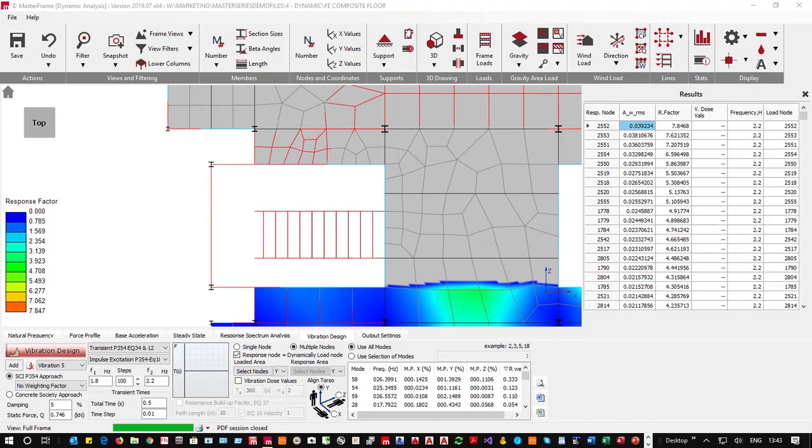Somebody's asking about this effect of the ribbed deck on the slab. Yes, the ribbing has a stronger strength, so you are going to span from here to here with the very deep and stiff component. But you have to remember that you also have the slab at the thinner surface spanning in this direction, and it will distribute some of the load accordingly.